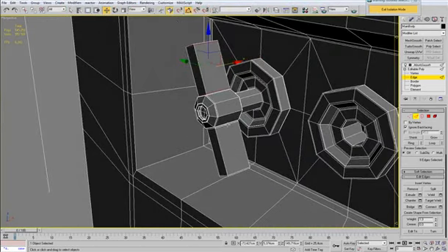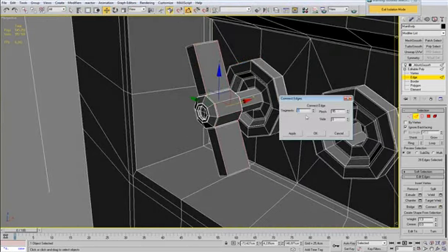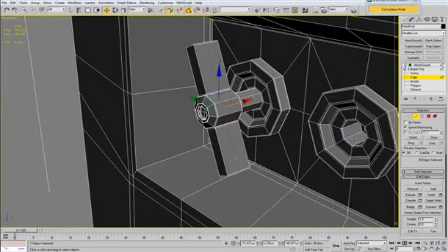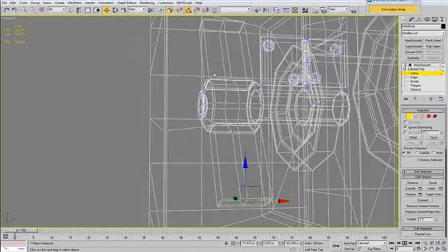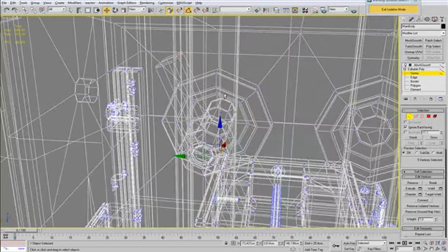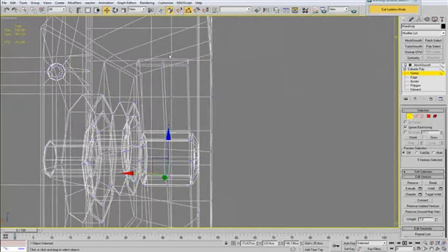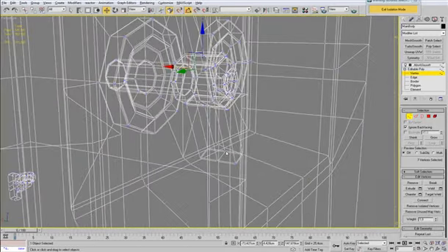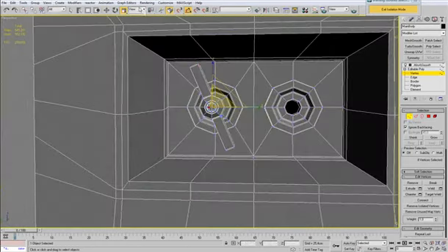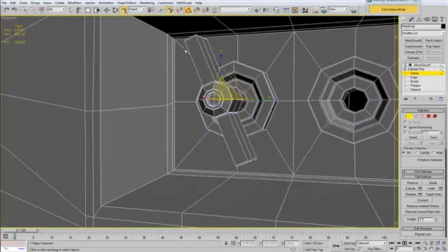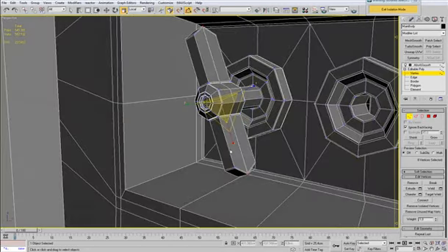And I'll try to match the shape closer. So I'm making a connect there in the middle, and I'm going to select the middle vertices at both ends, and I'll perform a scale on them on the local axis like that.